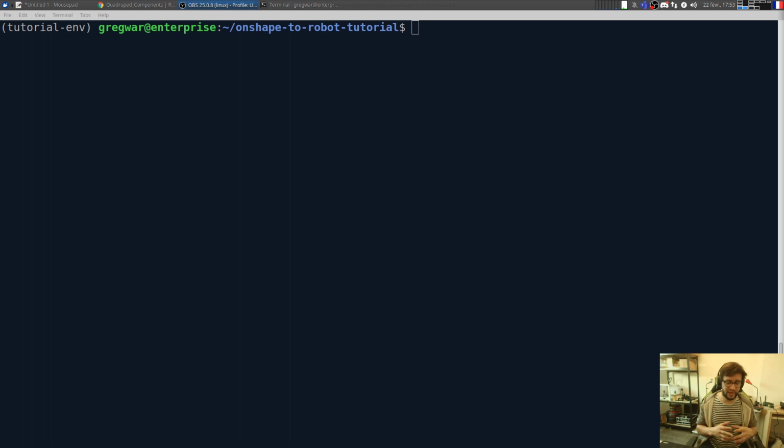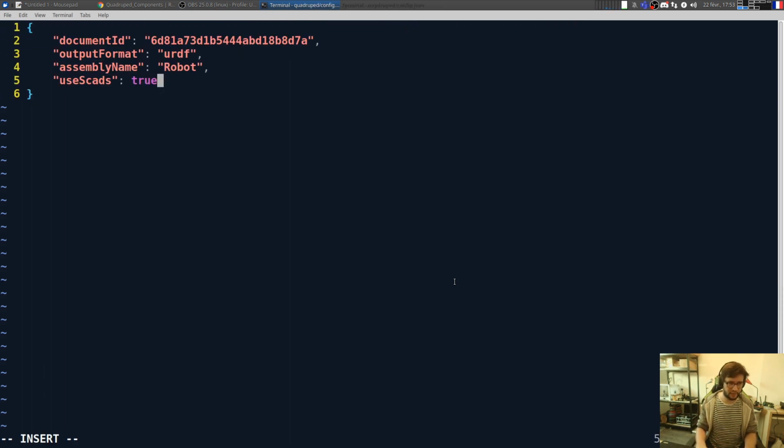Sometimes the robot can become more and more complex and the render can take a lot of time. So for this, we strongly recommend that you use the drawCollision flag. The drawCollision flag that you can edit in your JSON as drawCollision true is quite useful for both debugging your collision and lightening the load time of your robots. Actually, the effect of this flag is that the visual section of your URDF this time will be exactly the same as the collision section. So whatever onshape-to-robot is outputting usually in the collision section, it will be outputted the same in the visual section.